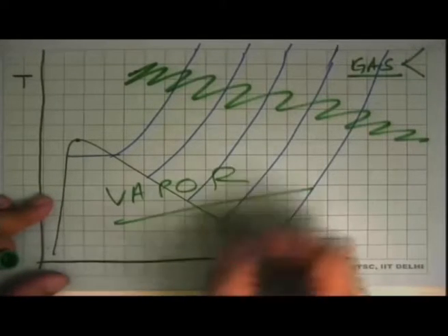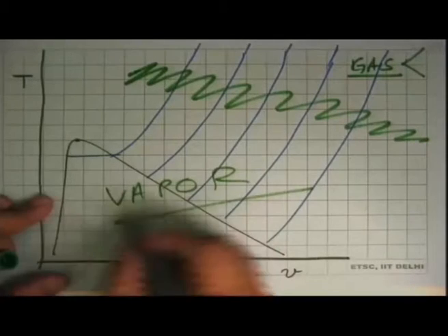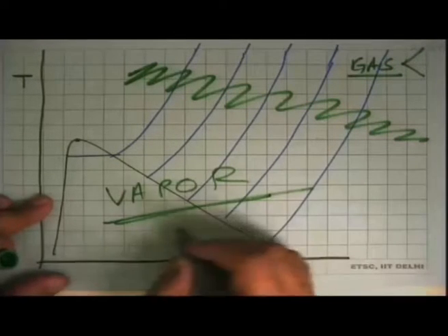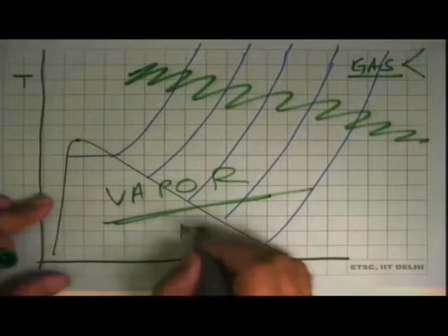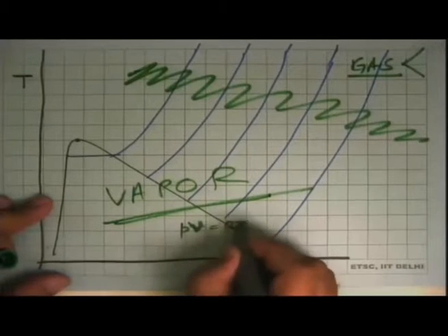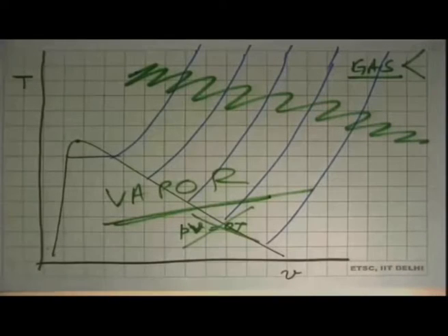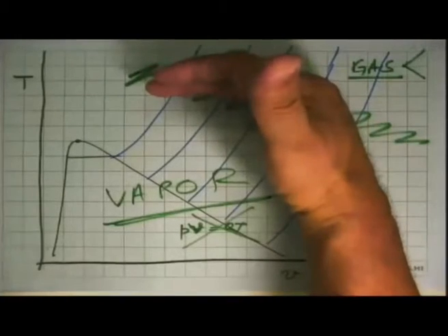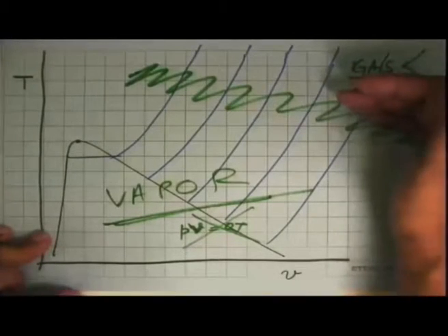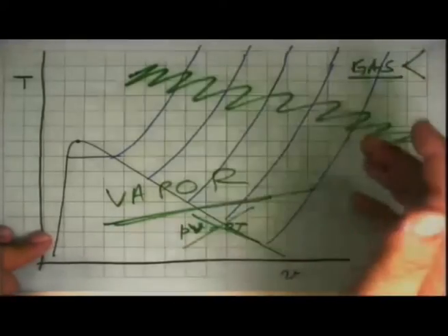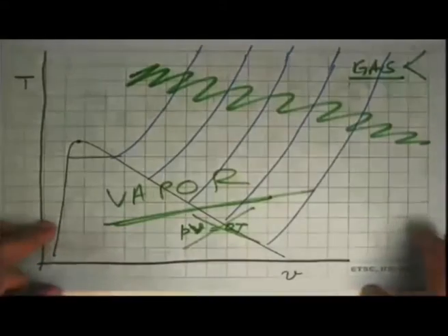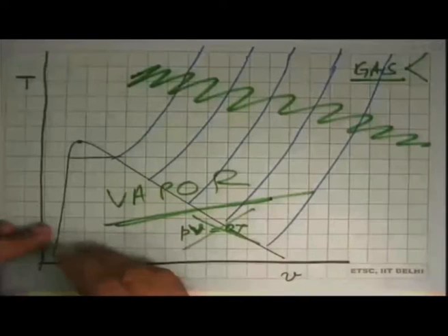But the fact is that in this condition where there is vapor-like behavior, we should not even think of PV = RT. Completely wrong. And that's why all property diagrams end at some point and do not give the chart properties beyond that, because then it is presumed that after this range of pressures and temperatures, the substance behaves like an ideal gas. You can start using ideal gas equations of state and you can forget about this part.